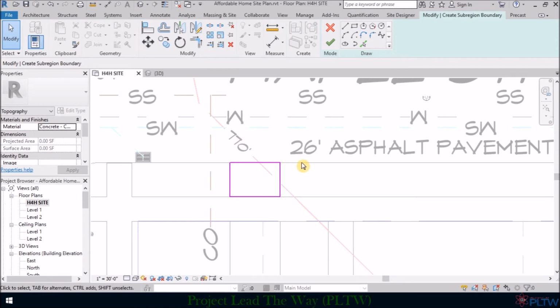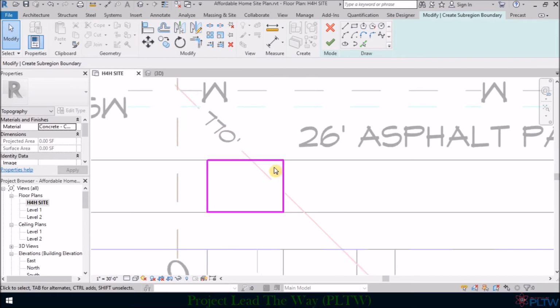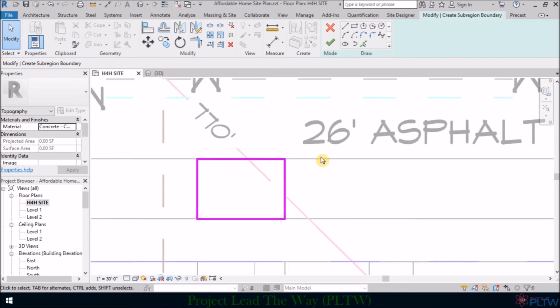Keep in mind that most roads, especially in this kind of location, this road probably has a curb and gutter or a concrete curb and gutter. So if you are constantly making a sharp turn here and you run over this corner of the driveway, you may over time destroy the integrity of the concrete, so it may begin to crack and look really bad. So creating that radius prevents that from happening. It can still happen, but it makes it less of a possibility. So I want to show you how to do that, but you can easily create a little diagonal line here and then just come over and do something very similar of what I'm getting ready to do.